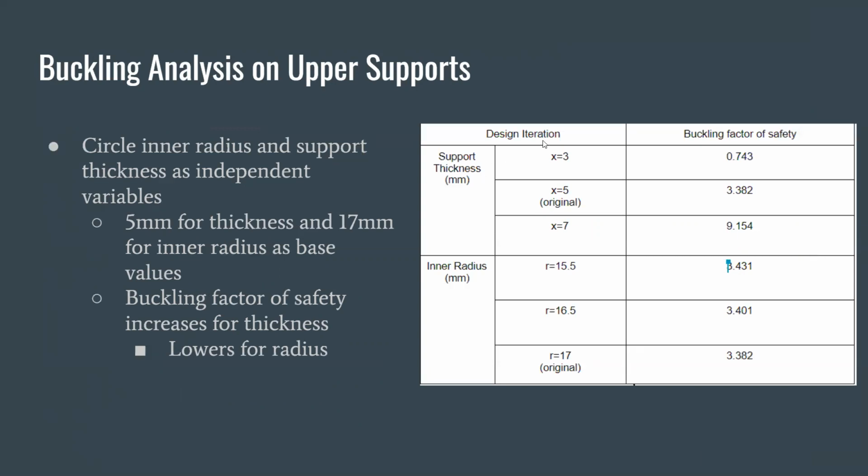And for my design iterations, it shows 5 millimeters for thickness and 17 millimeters for inner radius as the base values. I found that the buckling factor of safety increases as the thickness goes up, and it lowers when the radius goes up.